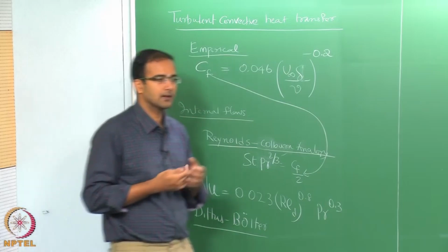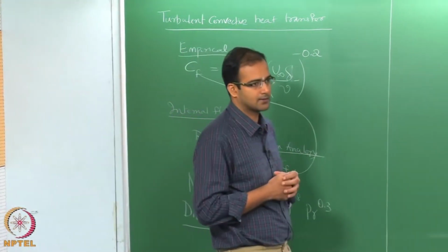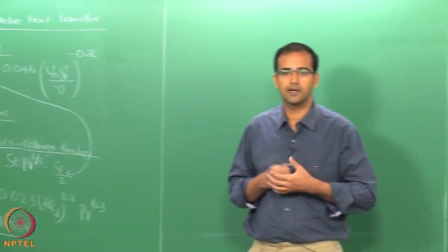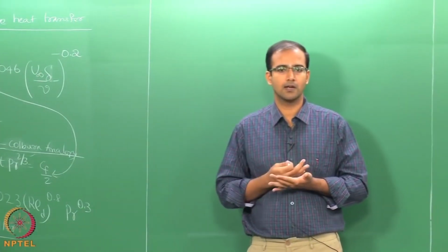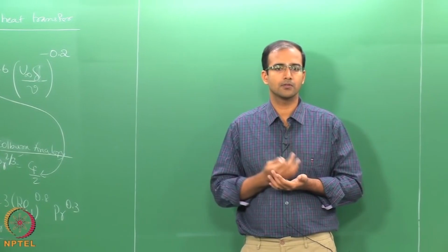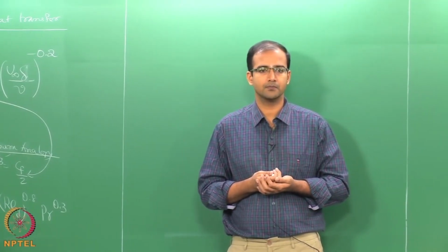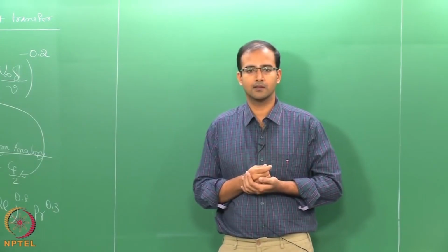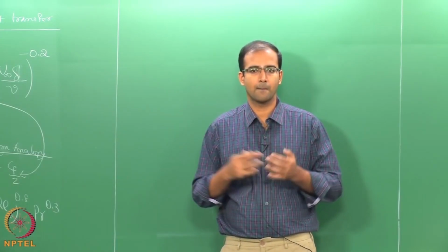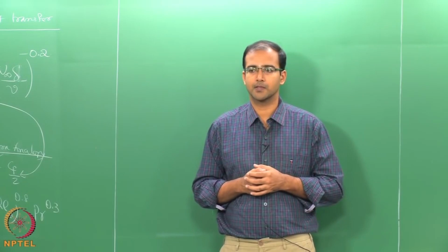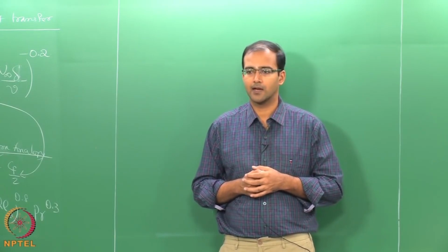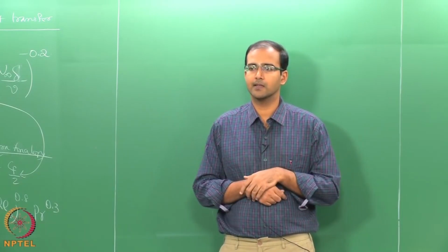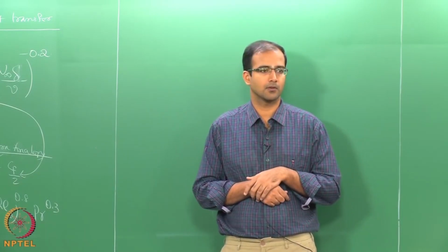We have to use the approximate methods. Okay. So, the only way to find delta as a function of the local Reynolds number is to use the approximate methods and then substitute this for the wall shear stress, and then we will have an expression for delta, and then we apply the Reynolds analogy, then we find the Nusselt number correlation.